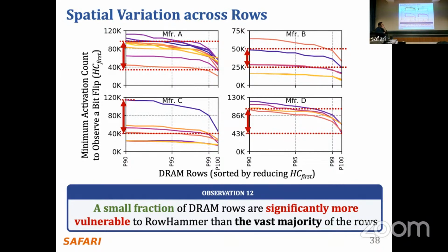In my mind, this kind of variation should be addressed or leveraged by configuring your already existing RowHammer defense mechanism for different aggressiveness levels for different rows. Or maybe you have a mitigation mechanism already taking care of all rows, and an additional, more robust, more proactive, more aggressive RowHammer defense that only takes care of a small number of rows. If you have a small number of rows with high vulnerability, you can give those special treatment. I'm still not sure about ECC though.